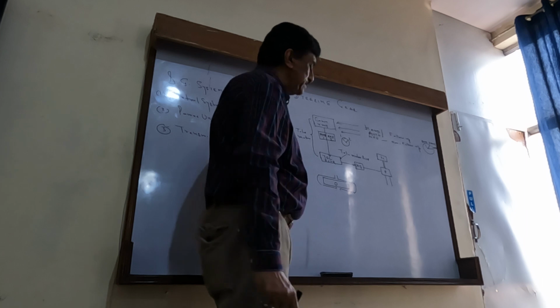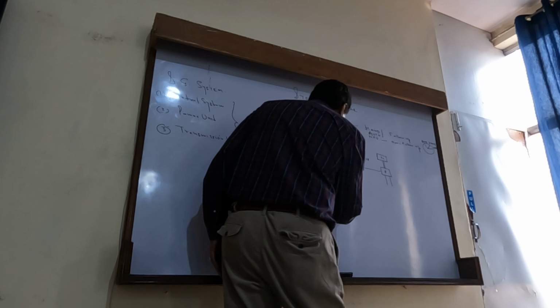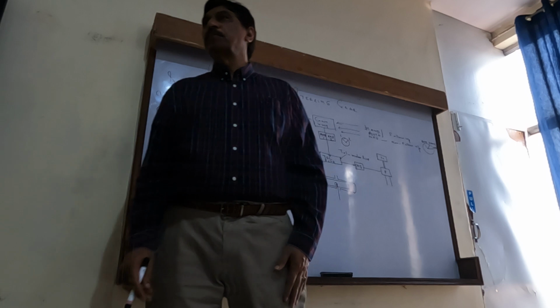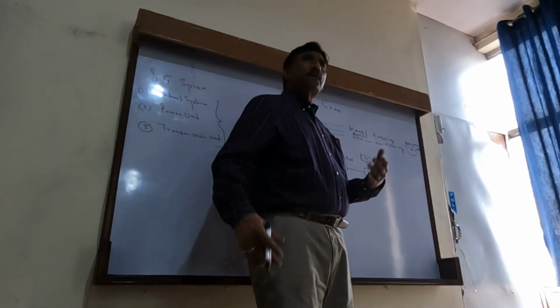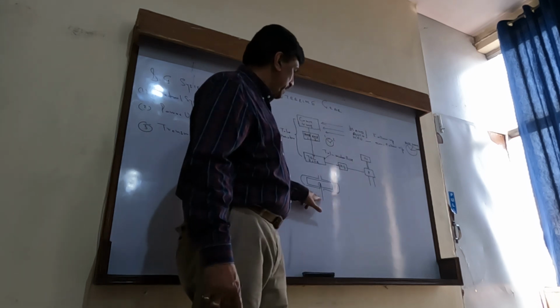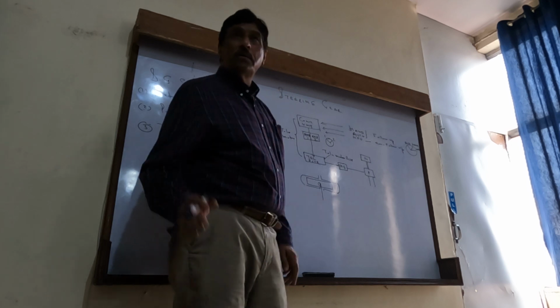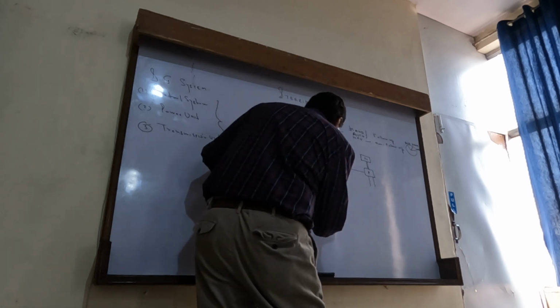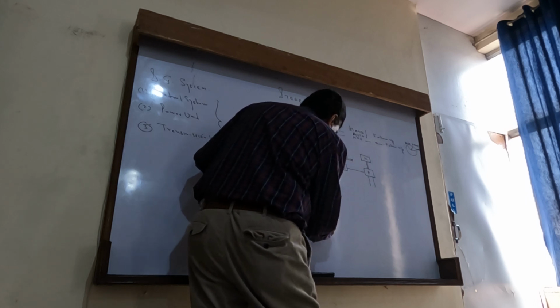This is 2 RAMs. This is one, this is another one, correct? And from here we have what is known as tiller. You need the tiller, right? So as the rams move, they will move the tiller. Tiller also has 2-3 designs, whichever it is, we will see later. But movement of this ram either this side or this side is controlled by tiller, which is connected to the rudder stalk. So we have the rudder stalk here. And this rudder stalk will move, and therefore the rudder will move.